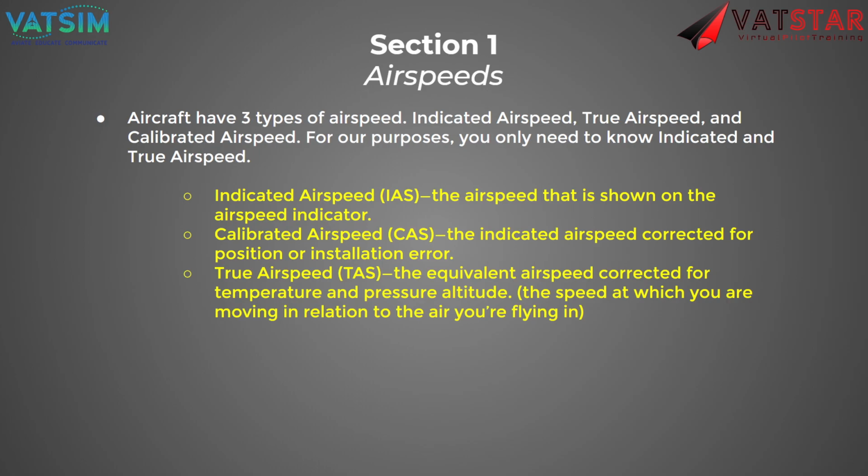Indicated airspeed is simply, and this is all you have to know, literally what is read on the airspeed indicator. Does that make sense? True airspeed is really what's important for calculating fuel burn, distance and times. Indicated airspeed is simply what is on the dial.